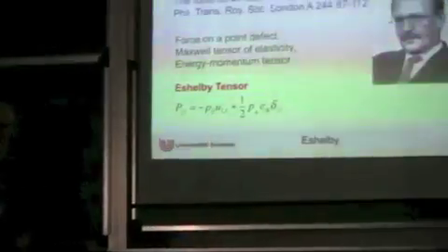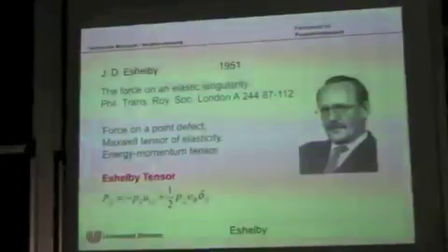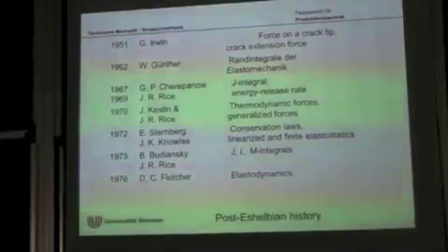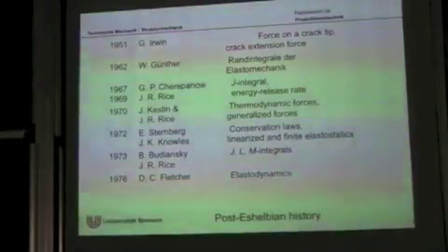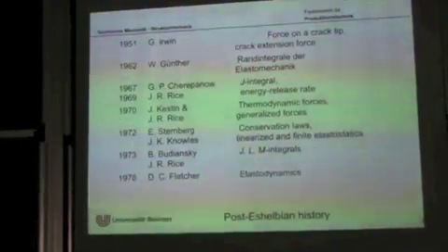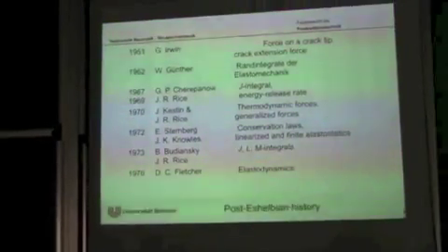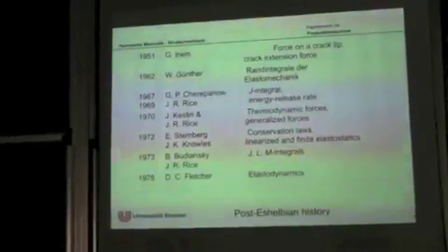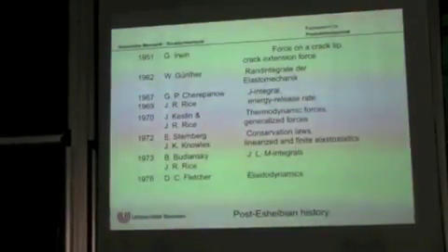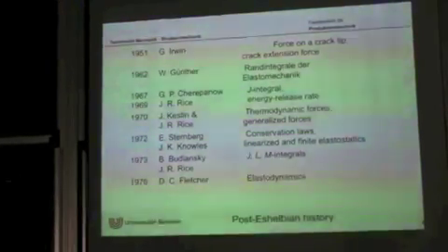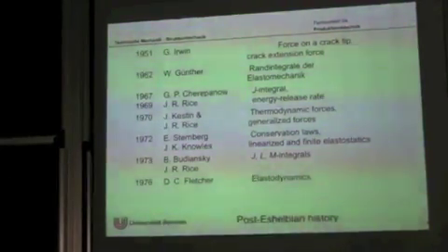And this integral over this Eshelby tensor tells you the driving force on this. Okay, then we have post-Eshelbyan history. Irwin immediately took up this concept and calculated the force on the crack tip by using the Eshelby tensor and the near crack tip field. He didn't introduce a J integral, but he expressed these forces on the defect by the stress intensity factors that those people working in fracture mechanics are very well aware of.